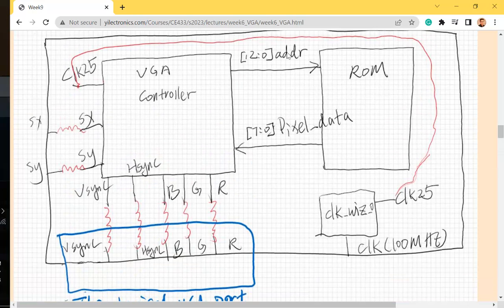Okay. So see, the address is available, data will get into the VGA controller. These are the number of rows and lines I want to use instead of 640 and 480, because the image is so small. So I just defined an 80 by 80 area to display that image, which will save some time and probably make it faster since I don't have to use all the pixels. I just defined two local parameters or constants in there to limit the counts.